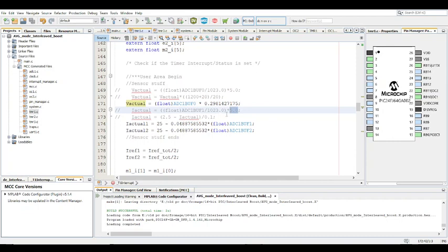some more advanced microcontrollers like digital signal processors have 12-bit ADCs. So this value here will be 4096 and this will be 3.3 volts, depending on what the microcontroller is, right? So you have to find out what that is. I think for some Texas brands it's 3.3 mostly, or I guess some have 3.3, some have 5, but just check and make sure this particular value